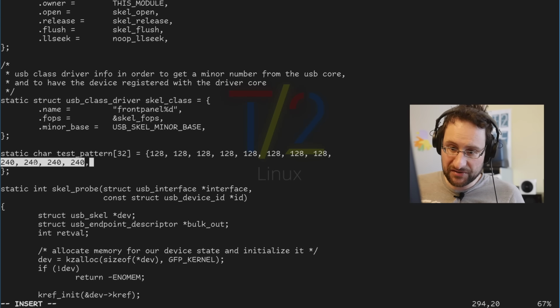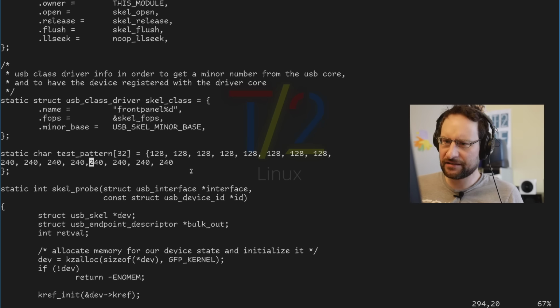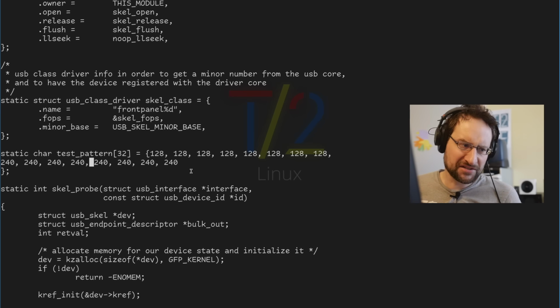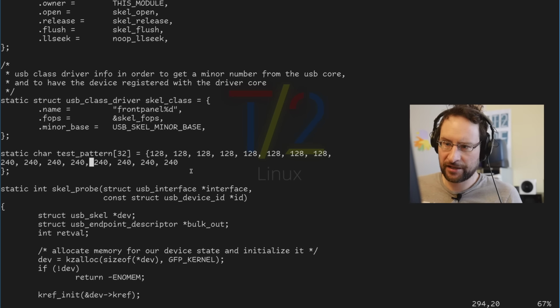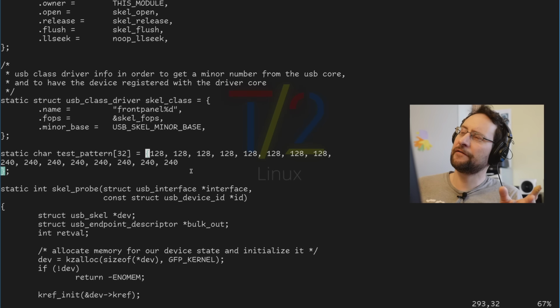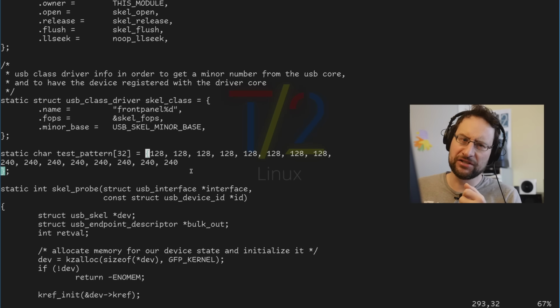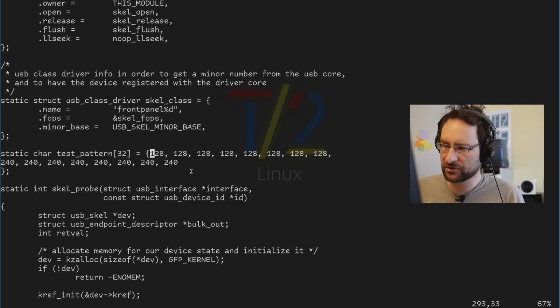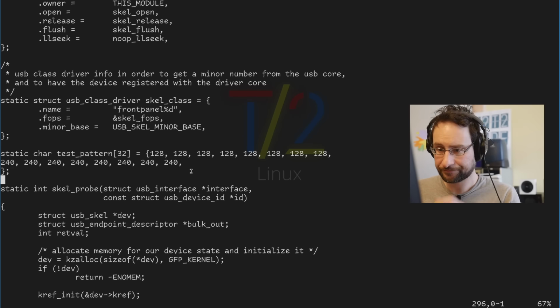From testing, I already saw that these LEDs are super bright, so I think the brightness is mostly useless on this front panel. Everything not zero, with my eyes I only see, maybe it's logarithmic or whatnot, or just a tiny voltage is already enough for the LED to light up. After 4 or 8, I don't see a difference. Basically at 8 it's already full brightness, so most likely that is pointless. But 1, 2, 4, 8, 1, 2, 3, 4, 8, the rest can be 0.